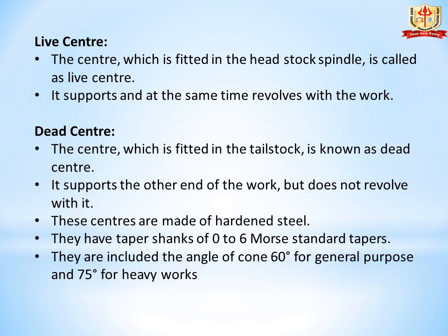Third point, these centers are made of hard steel. Fourth point, they have taper shanks of 0 to 6 Morse standard taper. Fifth point, they have an included angle of 60 degrees for general purpose and 75 degrees for heavy work.